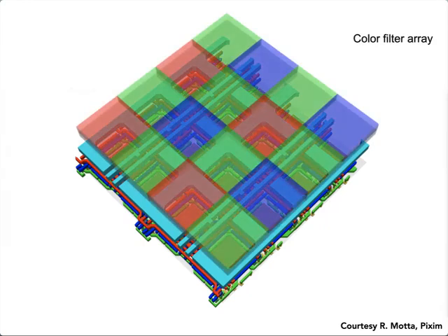Let's keep building up. This is a typical place for the color filter array to appear. You can see the RGGB structure that we talked about last lecture. Let me see, do I have a picture? Oh, I'll come back to it later. And then on top of this is where micro lenses would go. Unfortunately, this particular cartoon sequence lacks that, but the micro lenses would go on top here.